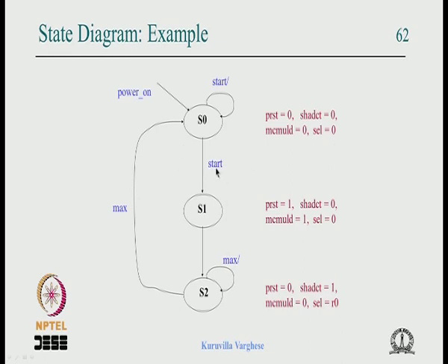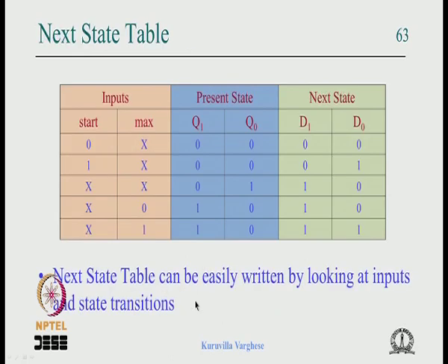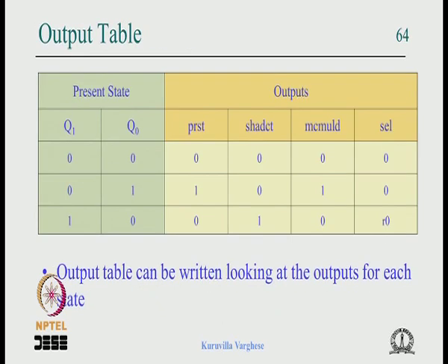It is enough that we write the hardware description looking at the state diagram. The moment you have drawn it, everything is captured, and you can describe the next state logic and output logic in a hardware description language looking at the state diagram. That is enough for the design. So that is it about the state diagram, the next state table and the output table.